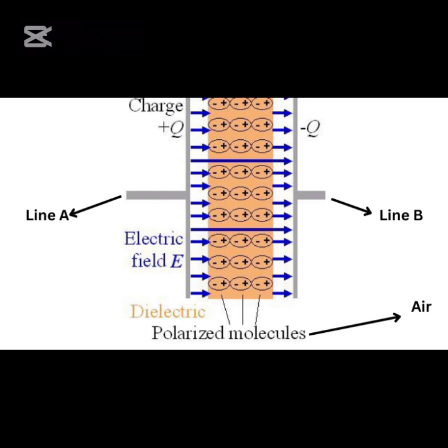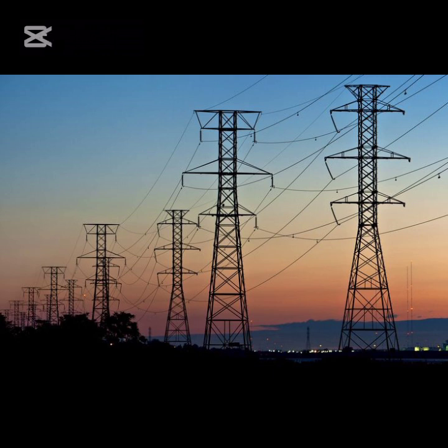The charging and discharging of the surrounding air is a simultaneous process, as the current is alternating current. This constitutes power losses by charging of the surrounding air. Now, note that the total capacitance of the line is proportional to the length of the transmission line. This makes the capacitance negligible on short lines and low voltage transmission lines. In the case of high voltage and long lines, it is considered one of the most important parameters.